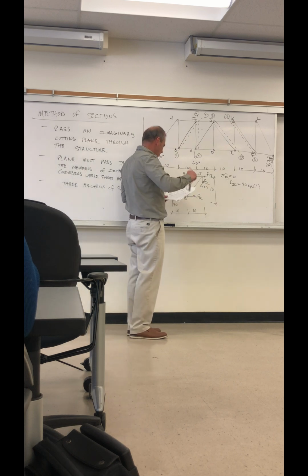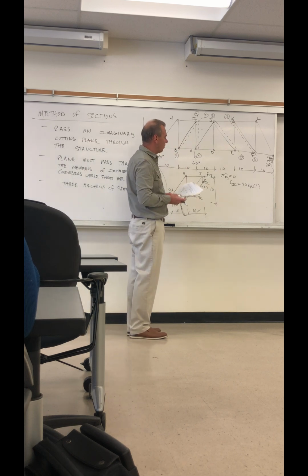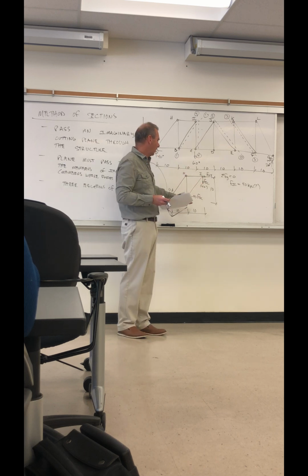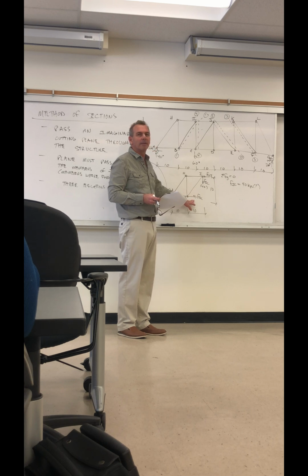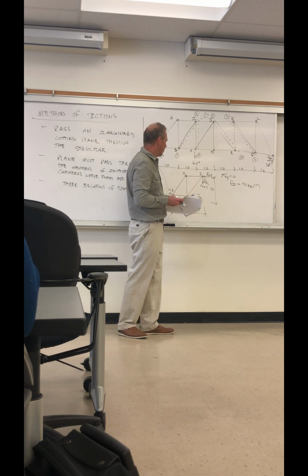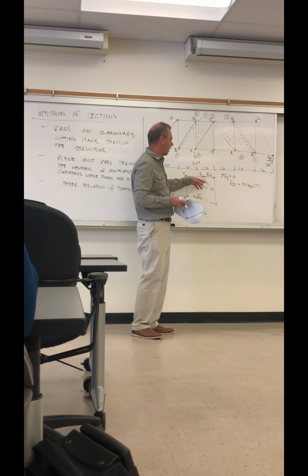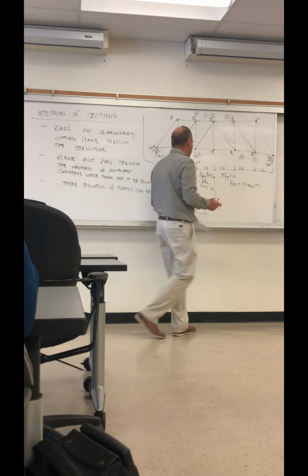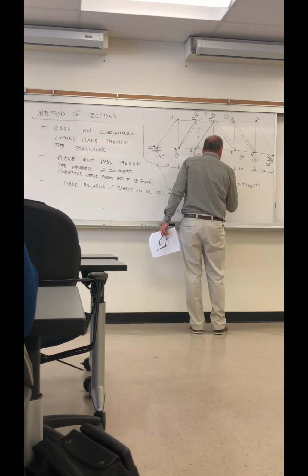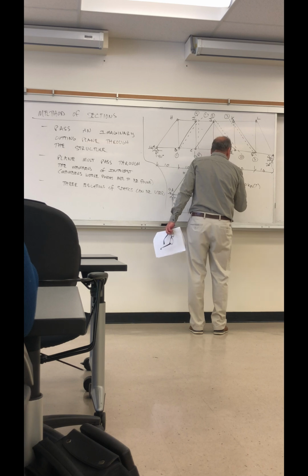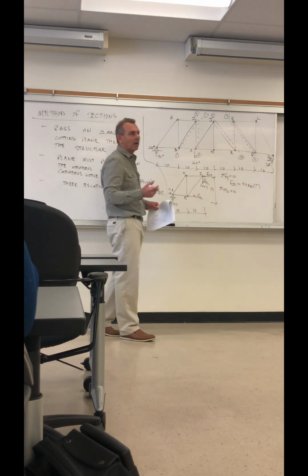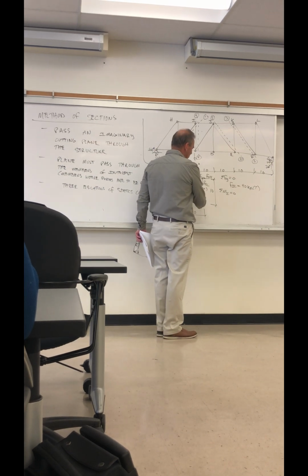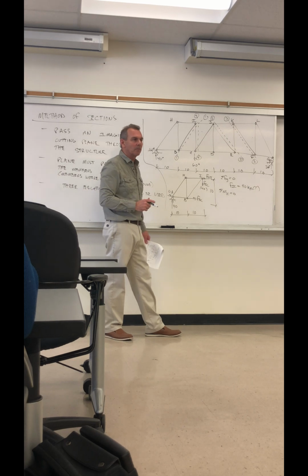Okay, so now let's say, and you didn't need to solve for F of IC first, sometimes you do depending on the section and the situation. Now let's say I wanted to solve for F of BC. I would just take moments about I, and I wouldn't even need to solve for C first. So a summation of moments about I equals 0. Again, everything clockwise equals everything counterclockwise. I'll start with the counterclockwise, because F of BC is the unknown I'm solving for.